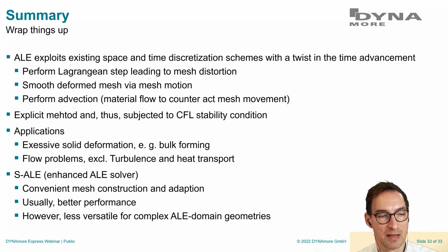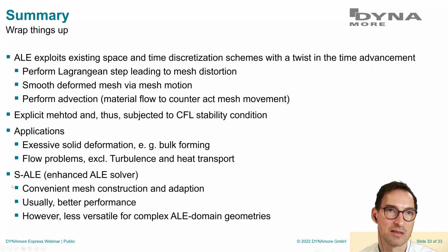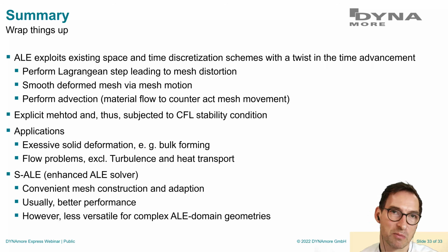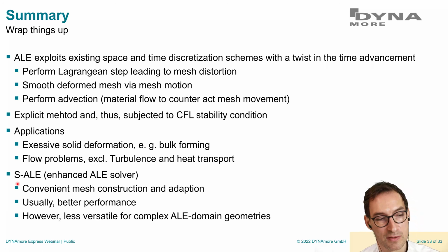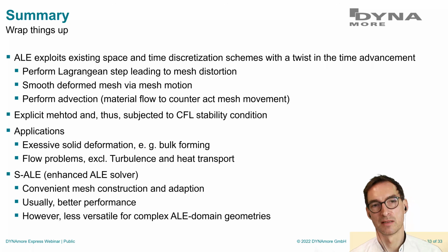Also try the structured ALE solver, which is an enhanced ALE solver, more convenient for different meshes and mesh refinement. It usually gives better performance. Not all the time, I even found cases where it was performing poorer than the original one. And one of the drawbacks of the structured ALE, although it gives better performance most of the time, is that it is less versatile when it comes to the geometry and mesh domains I want to analyze.